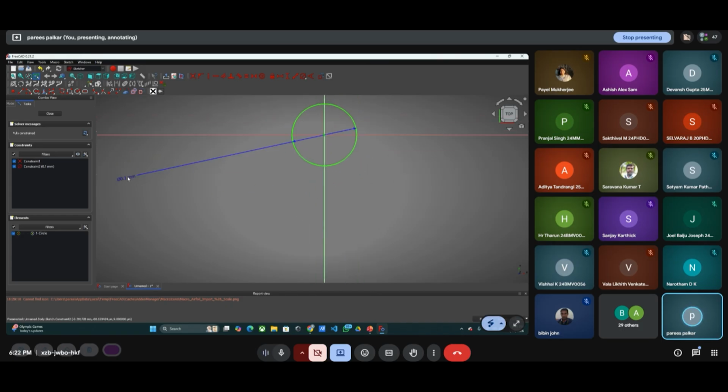So yeah, our circle has been created now. This circle is created at 0 comma 0. Now I will close this. If you are using FreeCAD for the first time, and the environment is loaded or your 2D sketch is loaded in a green section, that generally denotes that your geometry is fully constrained and we can move further with any operation.